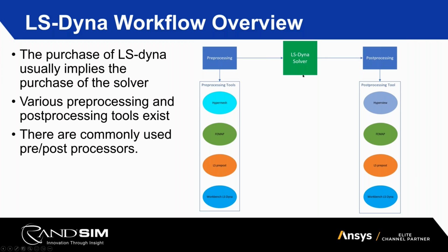So when you buy the software, and this is one of the confusing things that I've often heard, when you buy the LS-DYNA product, what you're buying is not a pre-processor or a post-processor. What you're buying is the solver itself, which means it requires an input deck, a bunch of files, which is going to be read by another program. So a pre-processor is what's going to create an input deck. An input deck is fed into the solver, which is what you're buying. And then when the program finishes executing, it's going to generate a bunch of files, which are read by a post-processor.